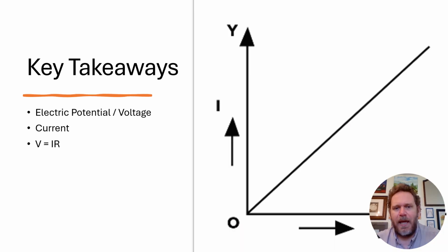Okay, so some key takeaways we need to remember here is that voltage doesn't kill you. It's the current or the charge that is often associated with it that does the damage and can kill you. Current is the thing you really most have to look out for. It's what can stop your heart. Low voltages can still provide a lethal current, so don't think, oh, it's only 100 volts, I'm fine, or it's only 12 volts, I'm fine. It can still do some damage to you.